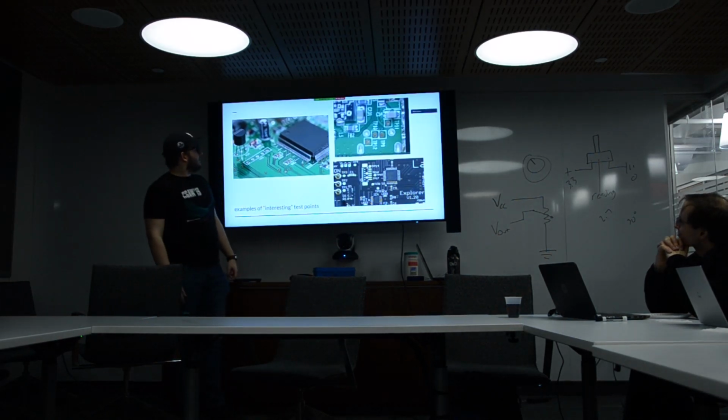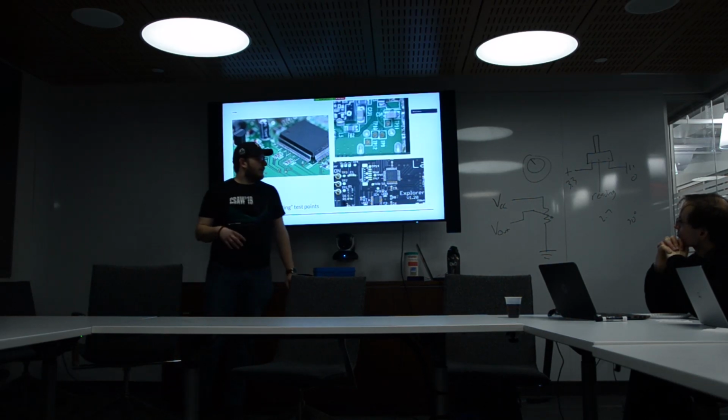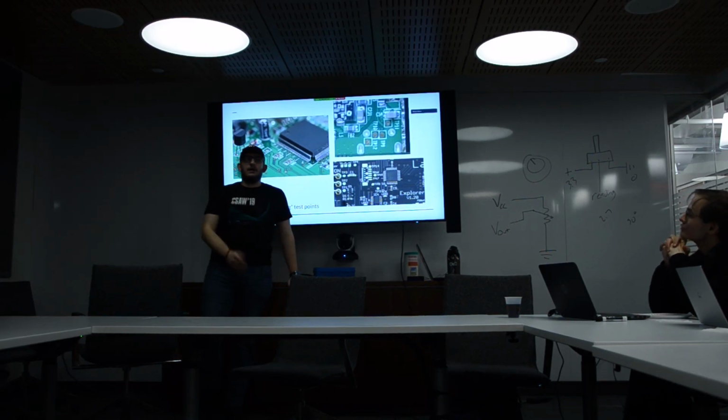We can do that with, I don't have any on this slide, but you can also do that in cases where you have QFN or I believe they're like BGA chips, where they have the balls, they have contacts on the physical bottom of the chip. You can actually physically heat the chips up and pull them off of the board to read them. Your device is never going to work again because the odds of you being able to get it back down in the same state are almost zero, but you will get that firmware off that device.